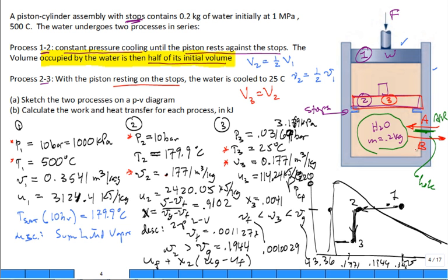You have two options. Once the hole is developed, which way is the fluid going to flow? Air rush in, answer A. Steam rush out, answer B. This is at state 3. This air is at 1 atmosphere pressure outside. Let's say it was in this room. Does everybody have enough time?